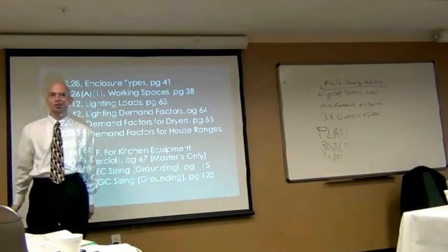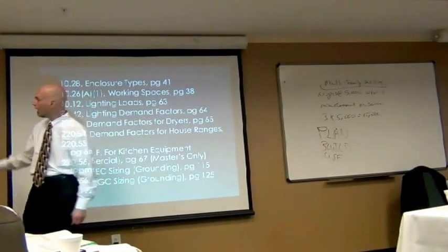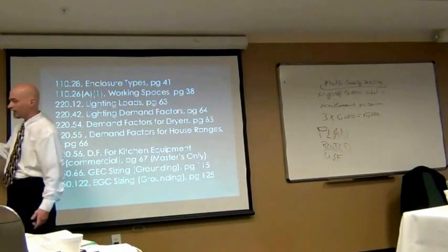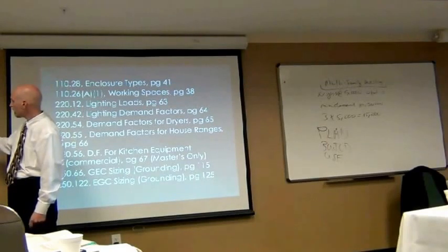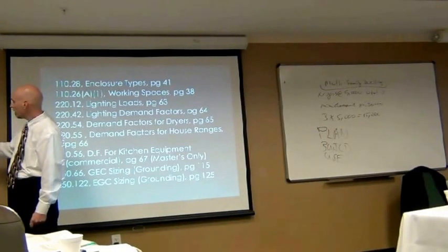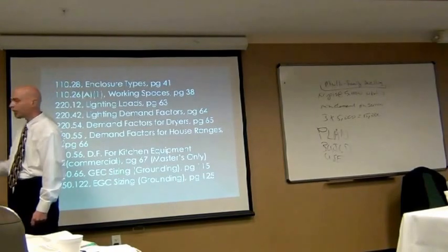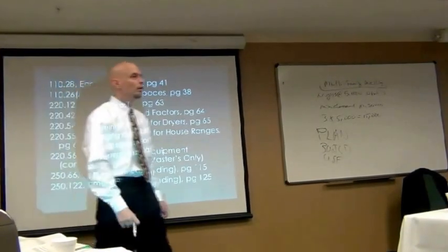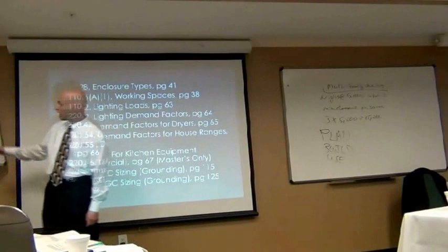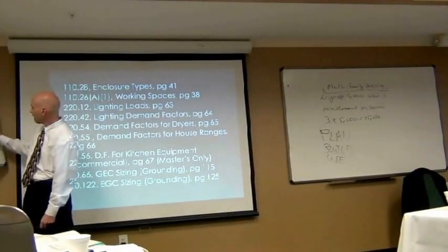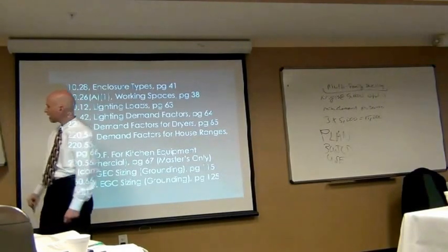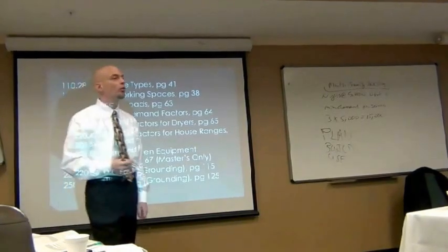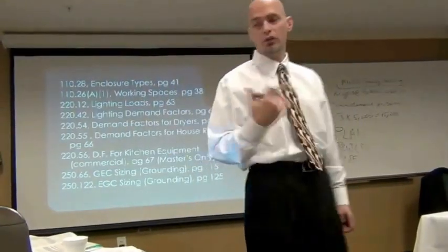just happened to me about that story I was telling you about that parking lot lighting circuit. What was in that conduit, it was a 1 1/4 conduit, by the way. I had 8 sets of number 6, and I had 1 number 10 ground. Okay? The overcurrent protection devices feeding this, I had a 50 amp, a couple of 30 amps, I had a 20 amp with a neutral, so it was 2, 4, 6, 8, and then of course I had number 10 ground. What size would I put that on according to this table?